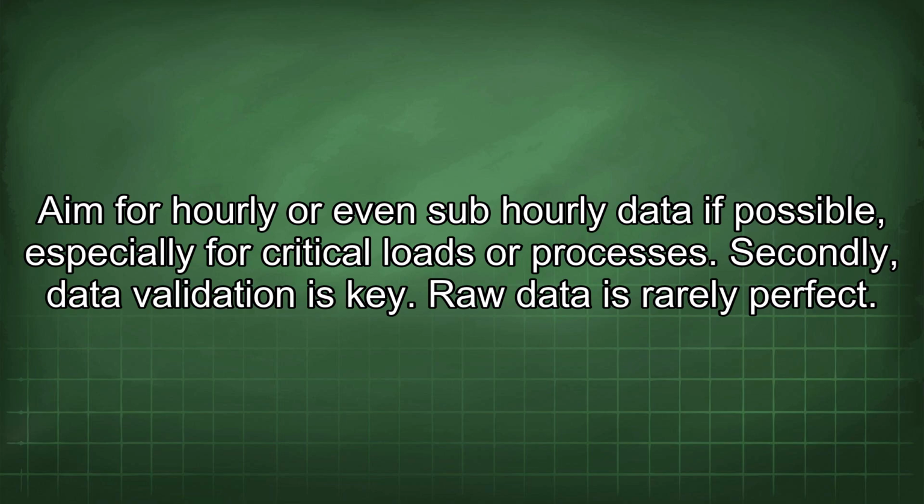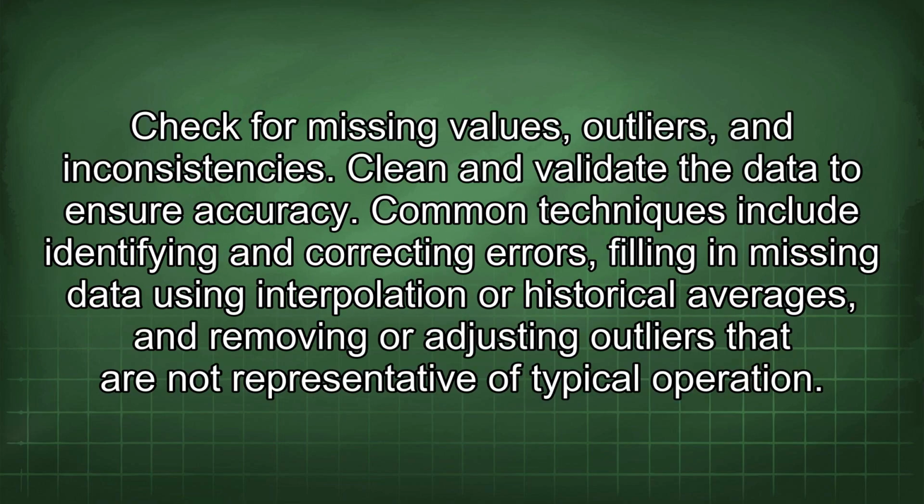Secondly, data validation is key. Raw data is rarely perfect. Check for missing values, outliers, and inconsistencies. Clean and validate the data to ensure accuracy. Common techniques include identifying and correcting errors, filling in missing data using interpolation or historical averages, and removing or adjusting outliers that are not representative of typical operation.